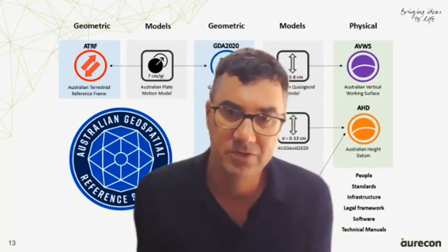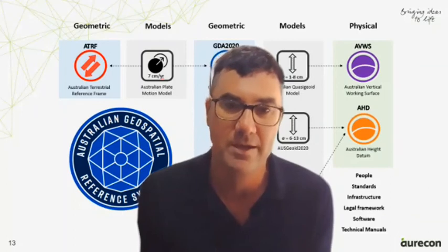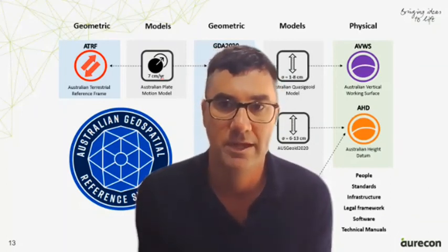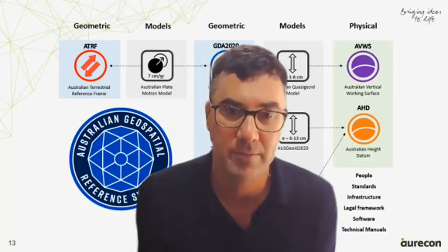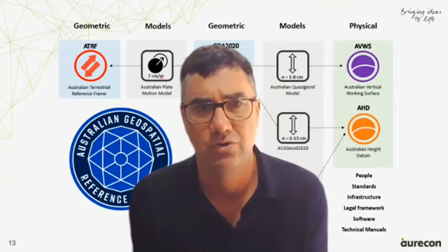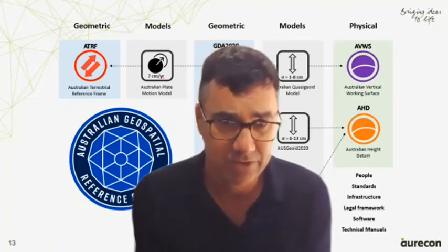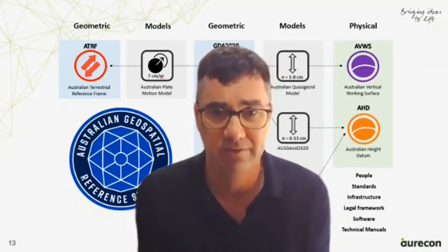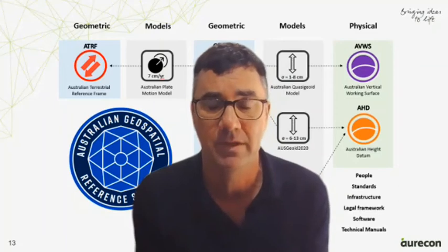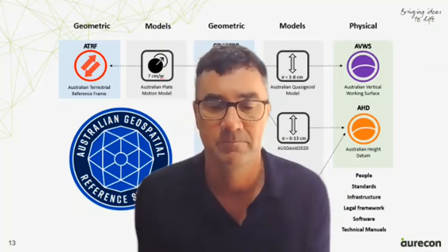So here's a couple of tips and tricks. First, grab yourself a GIS person or a surveyor. They're experts at understanding what GDA 2020 is and what it means. And they've got the tools to help make those transformations from older systems to the new 2020 or other systems as well. Please don't go to your CAD and make shifts or simple transformations in your CAD. There are robust tools that exist. We have them. They're freely available, so we can do those data transformations for you.